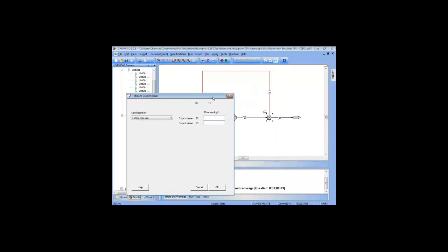There are two reasons this is a bad way to specify. Reason number one, you can specify something that doesn't match mass balance criteria. The second reason it's bad to specify what leaves a recycle loop, that means what stays in the recycle loop is X. There might be an infinite number of answers for X. There might be 5 answers for X. That's multiple solutions. That's hard to find. Whatever your starting value is will determine your final value. So the better way to specify a recycle loop is start by specifying what stays inside the loop. Let the mass balance determine what comes out.